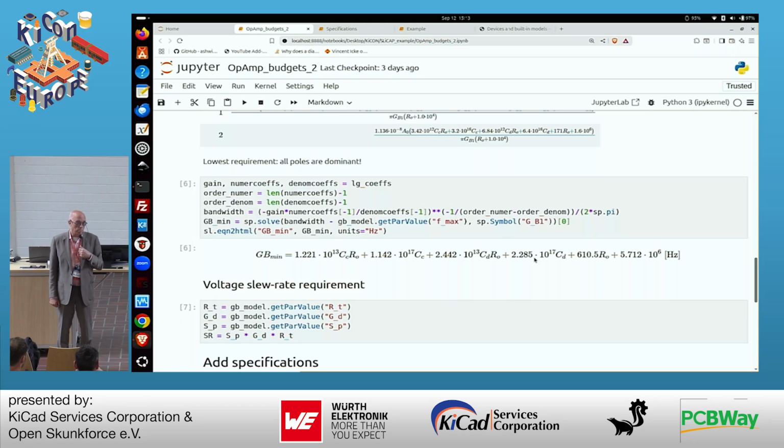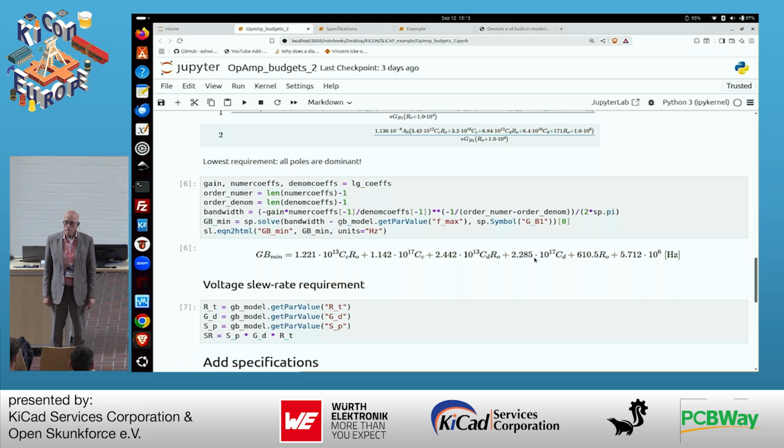So yes, you can, but you shouldn't solve 6 things in a nonlinear equation concurrently. It's horrible. This is the opposite of sensitivity analysis. You could do this in SPICE. What can you do then? Change the parameter and see what happens at the output, and that's called sensitivity analysis. But then you hope you change the right thing. You don't have an analytical expression. This works with analytical expressions.